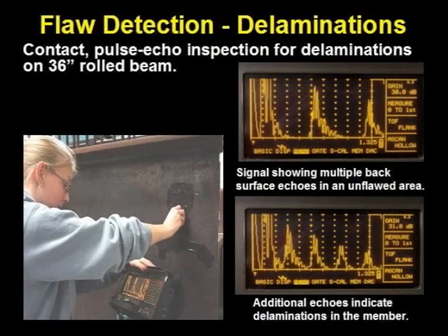Generally, the thinner thicknesses are more difficult to measure because the echo arrives while the initial pulse is still decaying. Special transducers are used with special calibration techniques to provide accurate measurements for thin wall measurements. This slide illustrates one particular flaw detection application.